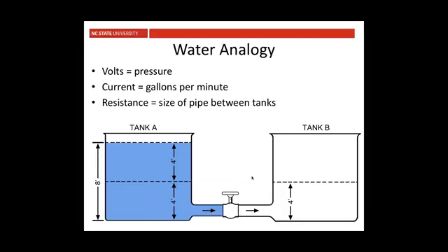And PV systems are interesting because you might have a 12 volt system, a 24 volt system, a 600 volt system, a 1000 volt system. It's all going to depend on how we wire up the PV modules. And we need to choose the other pieces of equipment in the class based on that pressure that we're building up. So we're going to pick a voltage for our system. We're going to design the system to operate at that voltage. And then we're going to choose wires and fuses and breakers and switches to be able to handle that amount of pressure. And we'll talk about current too. Current's also important, but I think if you start thinking about voltage and how do we build the voltage in the system, how do we get the right equipment, it's a good way to start thinking about different voltages in PV systems.